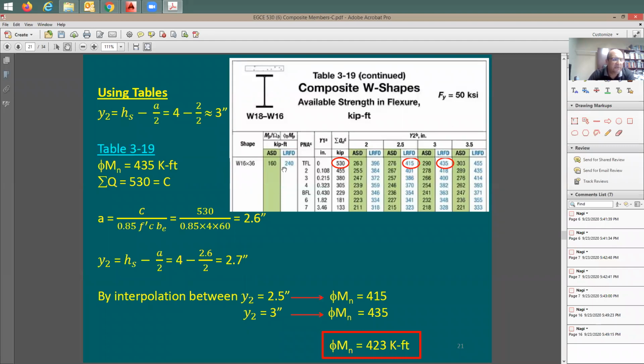The good thing is that this is going to be used here if you like to check the steel beam capacity in construction condition. So for the construction load case, you can just look here at this 240 and use it. You don't really need to do the entire analysis. You do phi times ZX, but it is also good from time to time that you remind yourself and do quick hand calculations just to confirm.